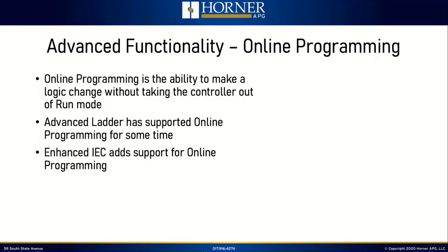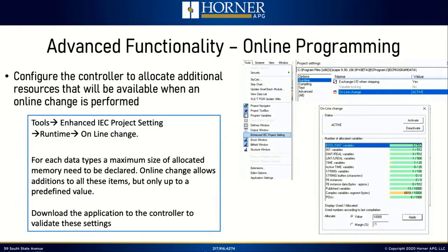The OCS Advanced Ladder and Advanced Ladder with tags in our products like the XL series, starting with the XL4 on up, and including the RCCs and the X5, those products also support online programming, only if you're using Advanced Ladder or Advanced Ladder with tags, that's variable based. It's not supported in standard IEC. It is now supported in Enhanced IEC. Okay, so that is a new capability in Enhanced IEC, and we're going to show you how it works here in a minute. But we'll talk about how it works first, okay?